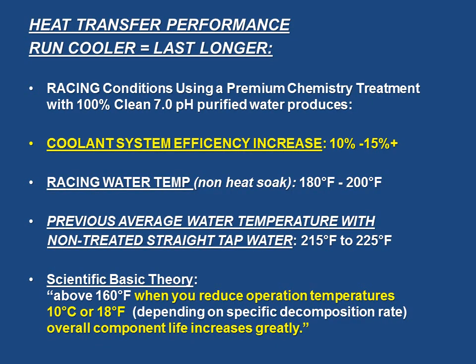Now, heat transfer performance. When you run cooler, you'll last longer. Racing conditions using a premium chemistry treatment with 100% clean, purified water produces the following. You will increase the coolant system efficiency by 10 to 15%. The water temperature with the thermostat open should run about 190 degrees, and this is without what we would call a heat soak or high extreme duty situation.